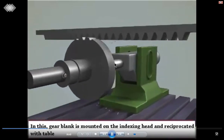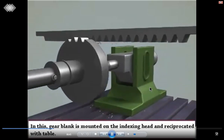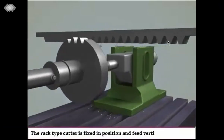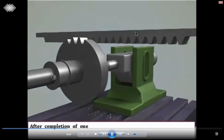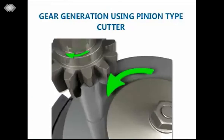the gear blank, or the gear workpiece, fixed on this dividing head reciprocates on the table along with this tailstock. So during this cutting action, the rack type cutter, or linear cutter, is fed vertically downward along with the depth of cut required, and it will generate the teeth by the reciprocating action of this gear blank on the table. After completion of one tooth, the gear blank and the rack cutter are rotated to the next pitch distance using the indexing mechanism, and this is repeated until all the teeth are manufactured.